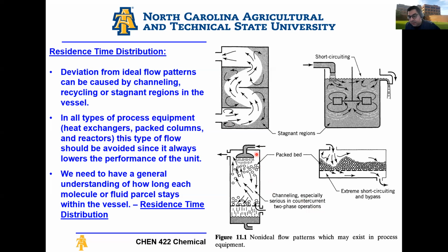On the other hand, moving on to other common non-idealities, is channeling. And you see channeling a lot, especially when you have gas and liquid. One thing you need to remember when dealing with gas-liquid or gas-solid systems is gas is smart. Right? And this is something you need to accept when dealing with the system. Gas will always find the easiest way out, and you need to find a way to force the gas to distribute equally along your column.